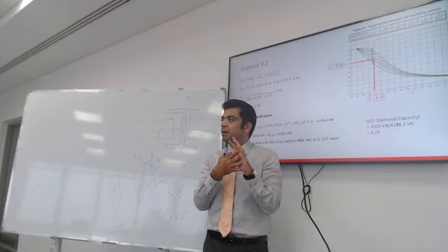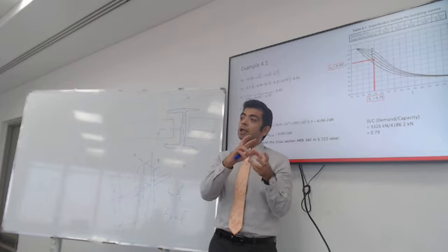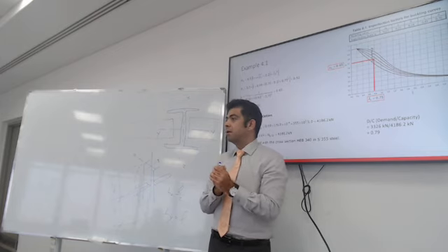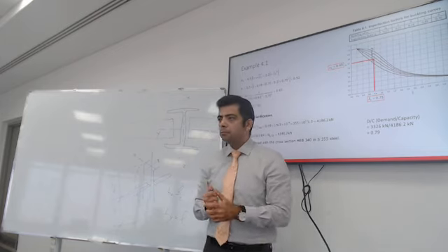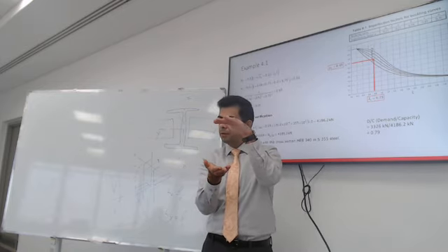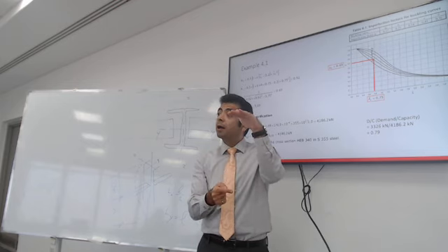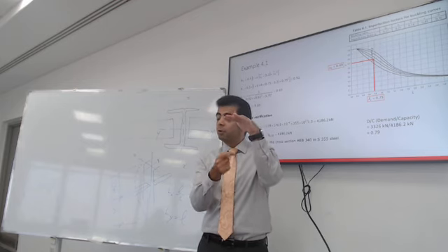You know what I'm saying? Because you're using a small member with a very big load on it, the connections might get in the way. Even that, because the depth is not very big, you have just limited dimension to length to weld.